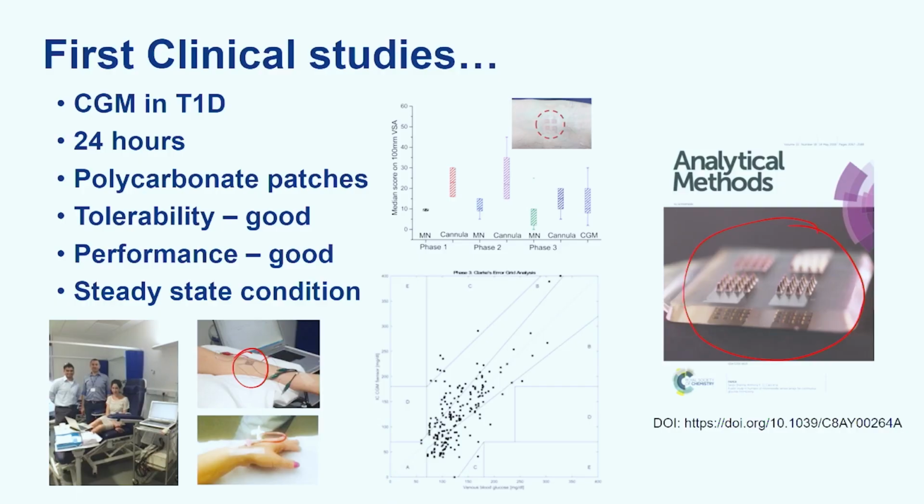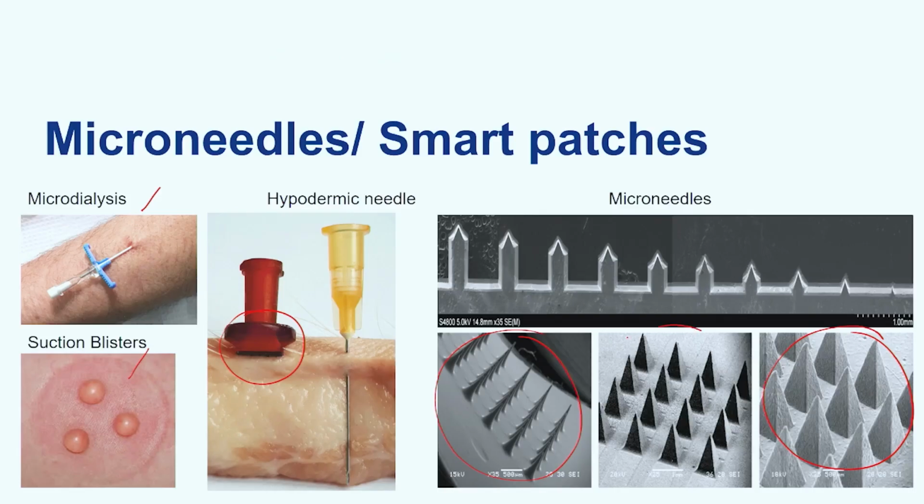They were molded microneedles, wherein we used electric discharge milling. I showed you the picture here. These are aluminum blocks which were electric discharge milled to get these pyramid structures. And how many of you have used SU8? One. SU8 is an elastomer, right? You mix the monomer and then you get a polymer. It's a very moldable substance.